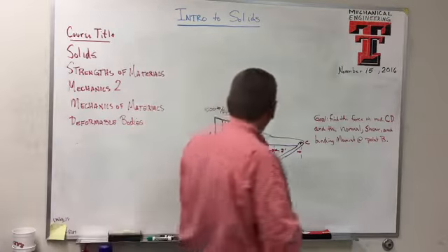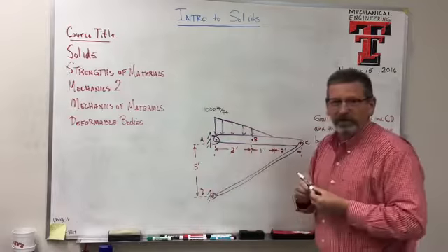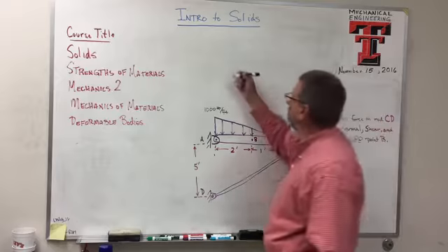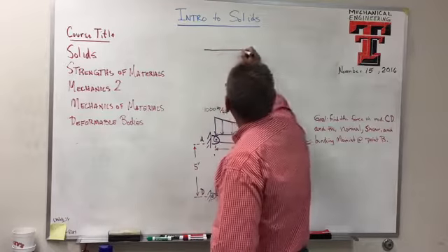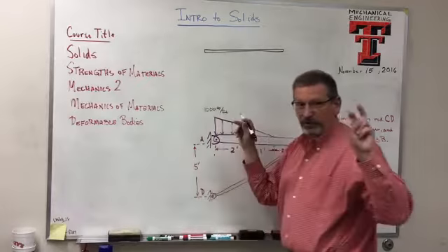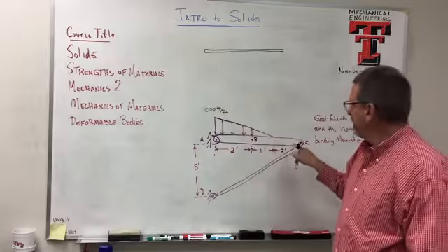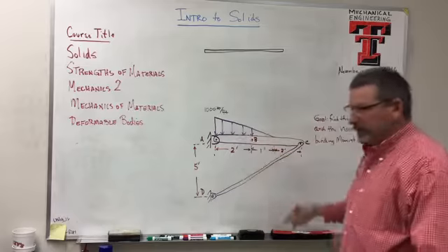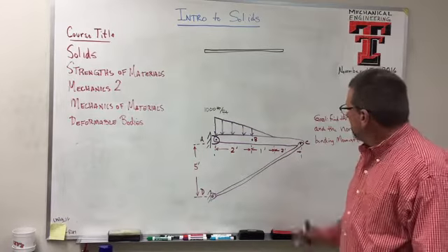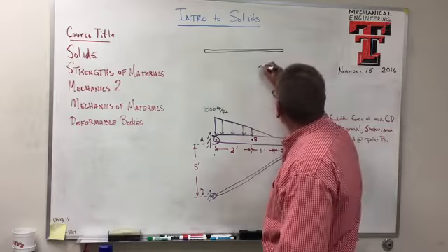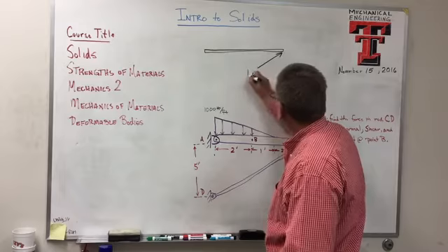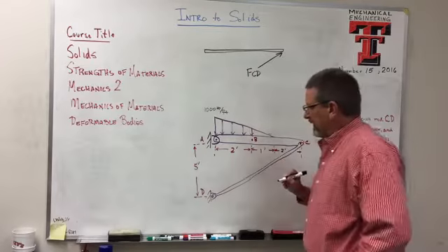Here we go, okay? Let's start off with, what's the statics? What do we start off with? Go. Free body diagrams, that's right. Okay, here we go. Let's draw a free body diagram. And the body that we want to free up, right, our free body, is this beam right here. And if you were that beam, what would you feel acting on you? Well, I feel a compression member that's pushing on me. That would be member CD, okay? We'll call him force in CD.